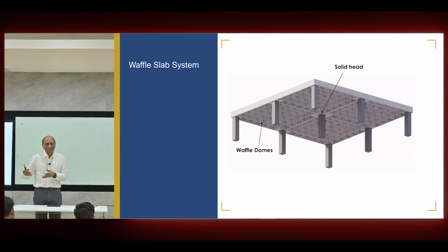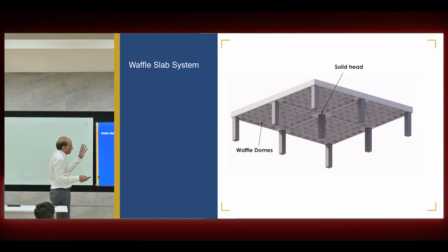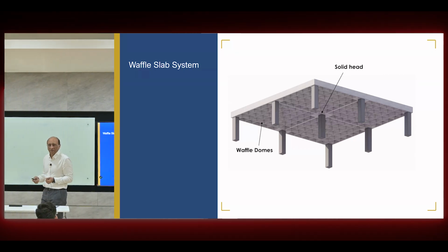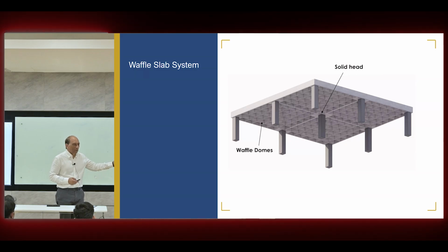So the contractor who had a formwork, they will get all the project because Waffle slab became very popular. Hospital buildings, other places, very common, very popular. Heavy loads can be carried, libraries, because they're very stiff, very strong, still lightweight. Okay, 9, 10 meter, you can go, 12 meter, you can go with a Waffle slab.